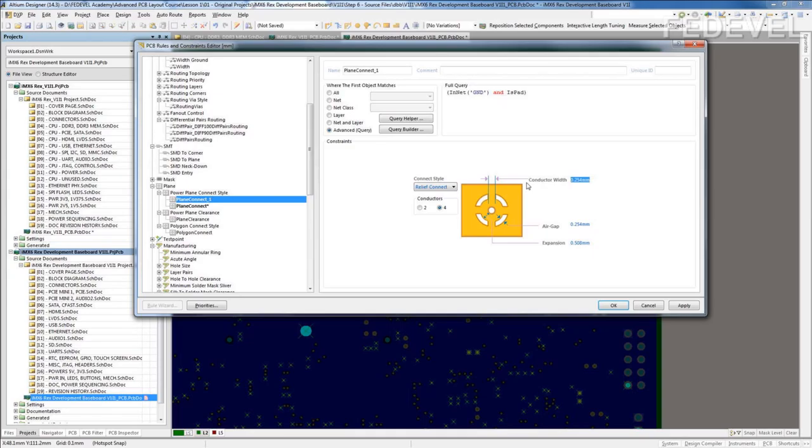These numbers here, you may want to calculate them. It really depends how high current will flow through these pins. So sometimes keep these tracks which are here wider if it's power. In this case it's power because it's ground. And I will call it, for example, pad. Now watch what will happen.